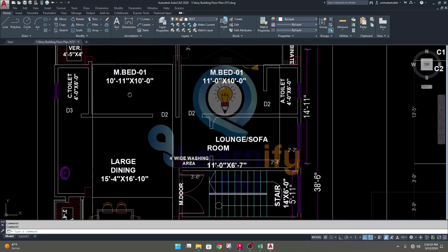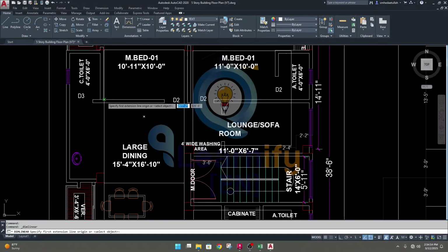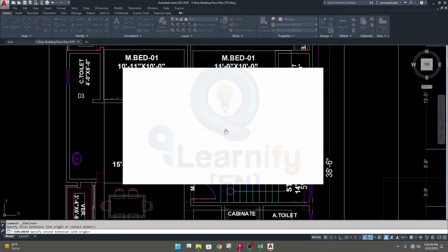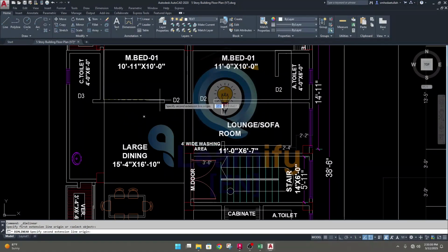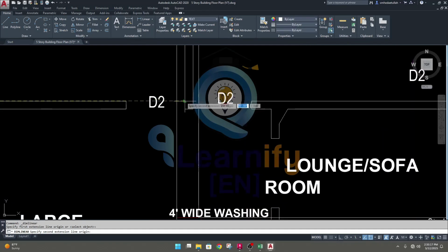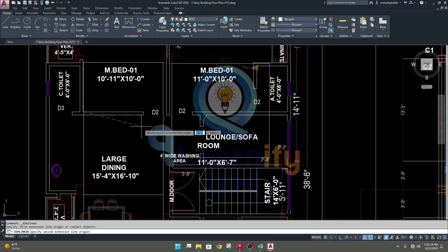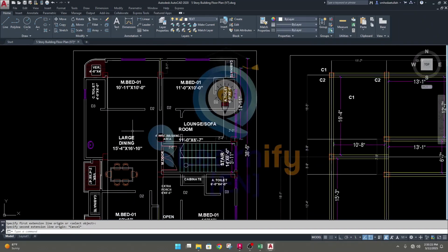First of all, we have to find out our wall length. So from here to here it's 7 feet and 10 inches, and I will consider till this point because they have a door, so our slab also will carry this load. So from this point to this point, almost here, 10 feet 10 inches, that means let's say 11 feet total length.